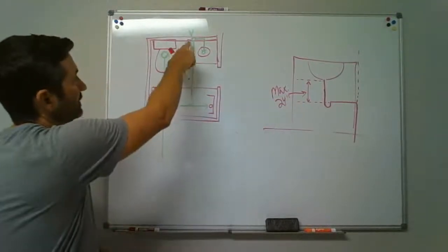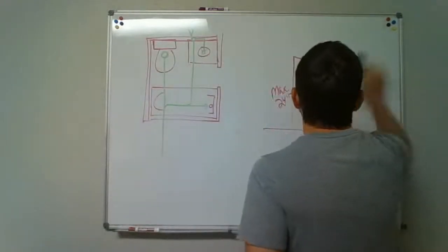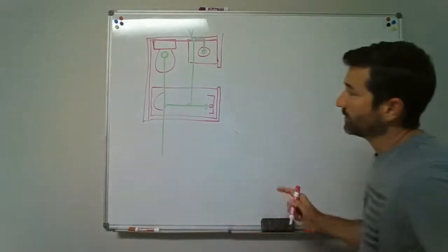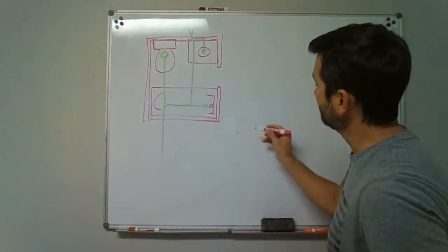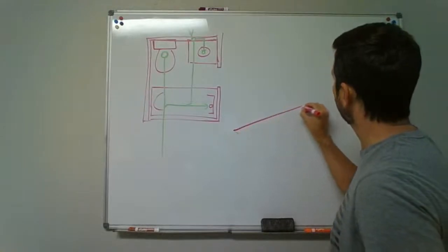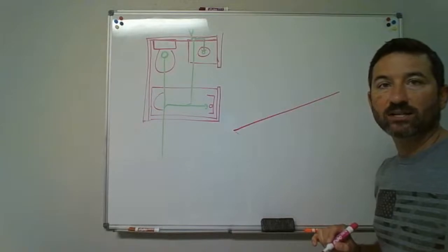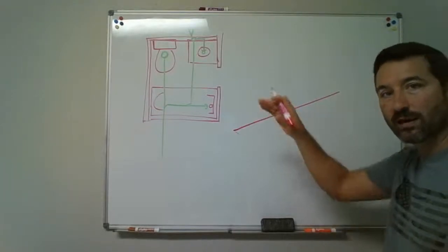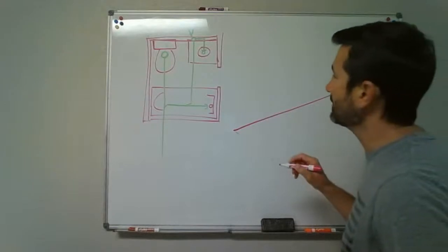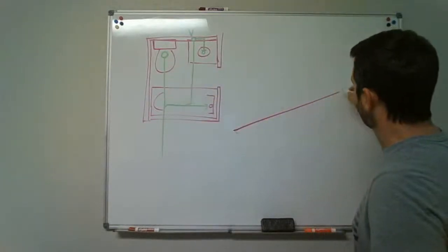So there's the vent on this lavatory sink. Let me draw it from a little bit different perspective. Okay, so now I'm going to draw this right here. Let me throw it up on as close to a 30-degree angle as I can. When you get in and take a class, you'll get some isometric paper, which will have 30-degree lines on the paper, which will help you get set up. So this line right here is the one I'm drawing that kind of goes up at a 30-degree angle.